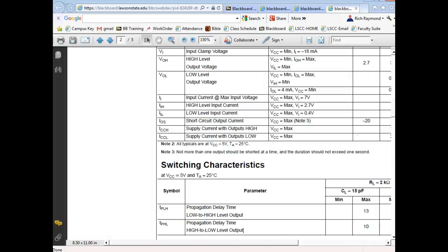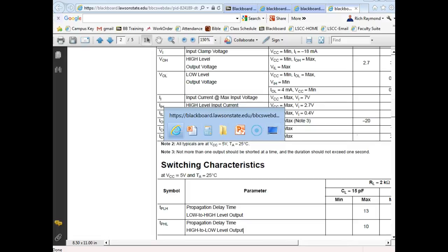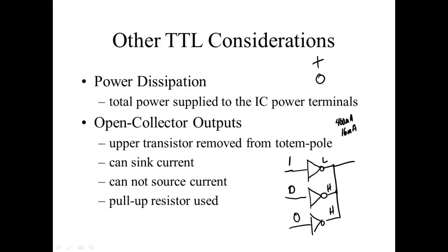But this would be beautiful if it worked without messing up the gate. Because what I've got right here is any high will give me a low. If this worked, right? Because normally we would think the low would win. So if this guy right here is connecting this to ground and these two are highs, then normally we would think it would pull these two lows. So that means any high would give me a low, which would be an OR gate. You follow this so far?